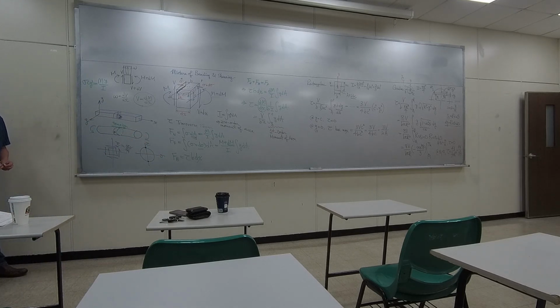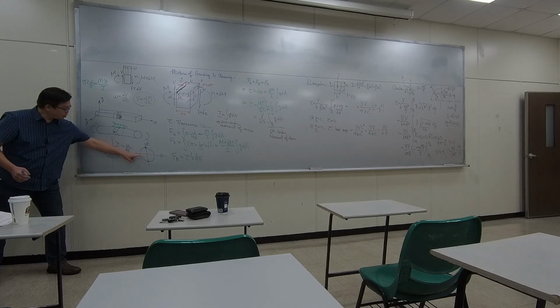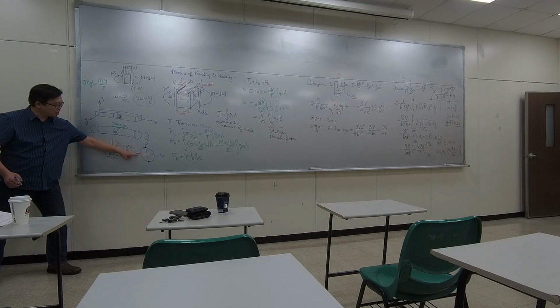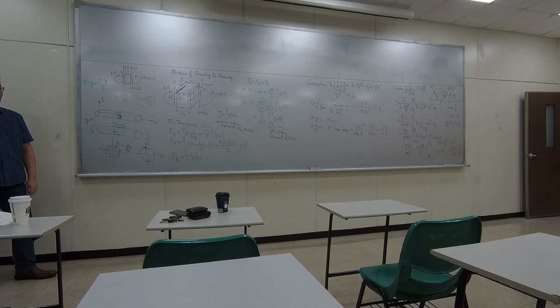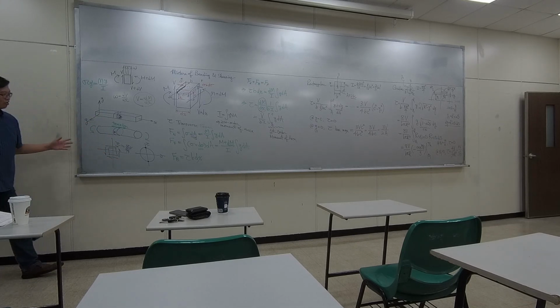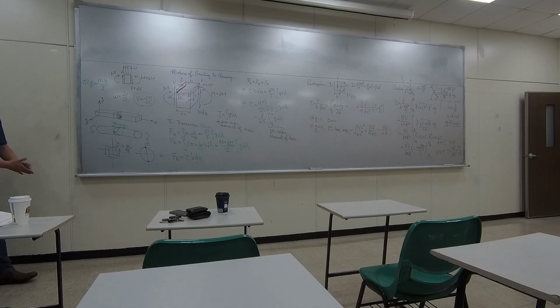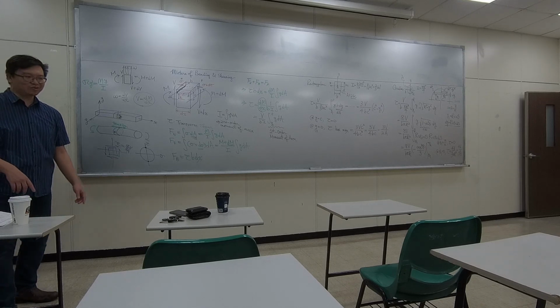Okay, and if you want to compute principal stress, you still have principal stress, the first and the second one, one positive, one negative, and the maximum shear is going to be 4V over 3A. Okay, so if you truly want to get the final answer for the problem from the exam, I think this is how you get it. So that's a quick answer to yesterday's question.